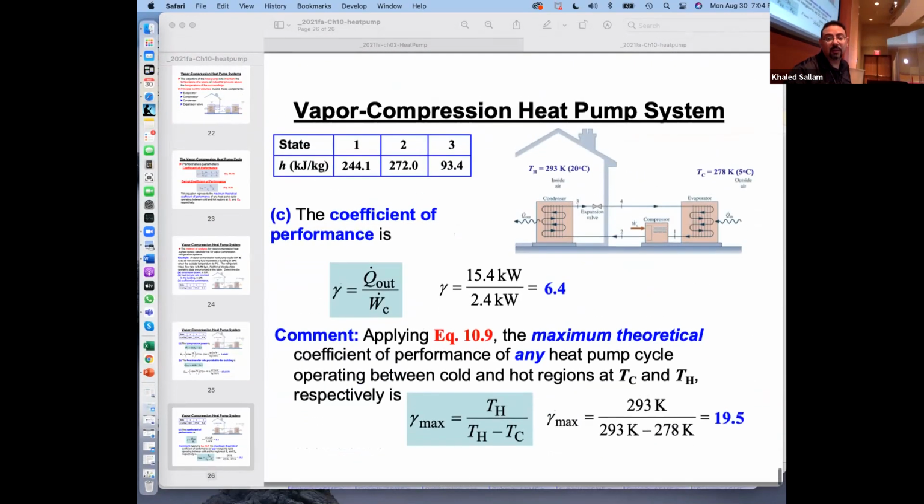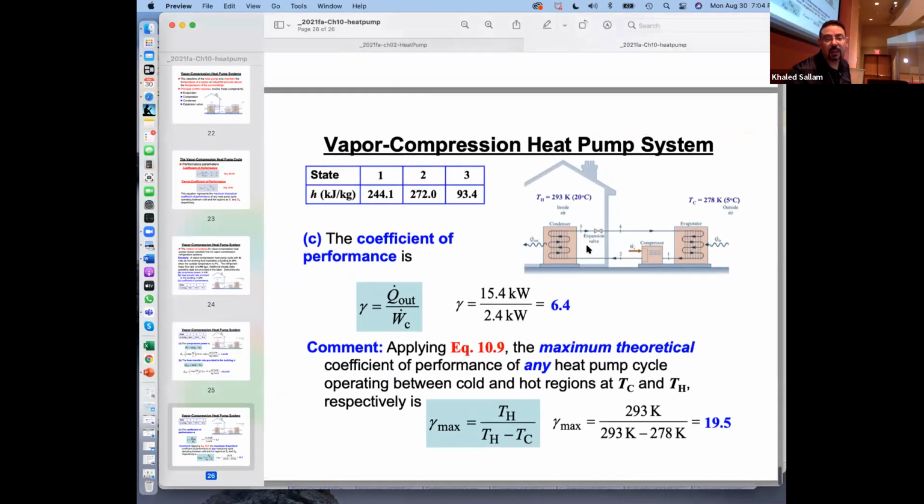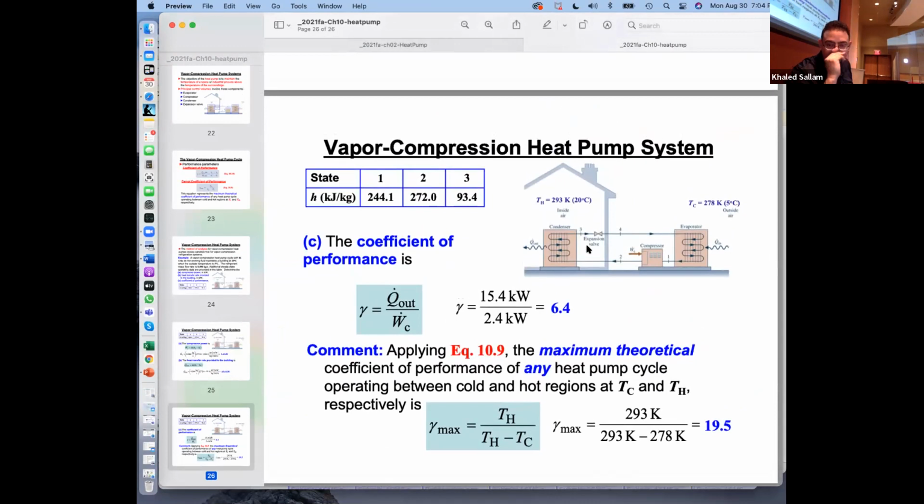I don't know whether they have a good drawing for it or not. I think maybe in the book they have a good drawing. Maybe not in the slide, but if you go to the actual textbook, you will find a good drawing of the throttling valve. But the point is, you are sending the flow through a very tiny hole or through a very long, tiny pipe so that the pressure just gets killed by going through it.